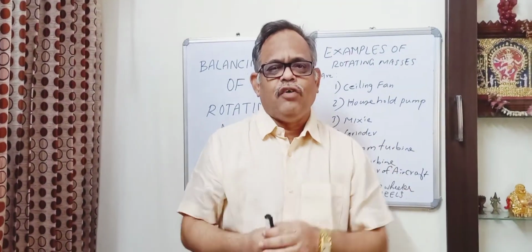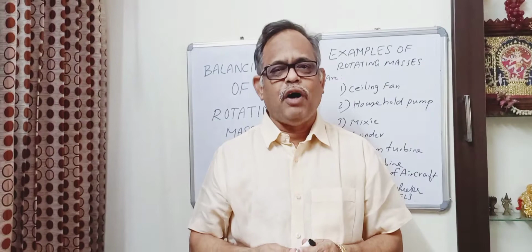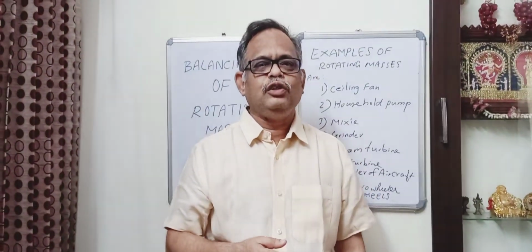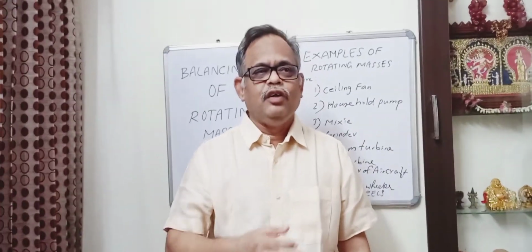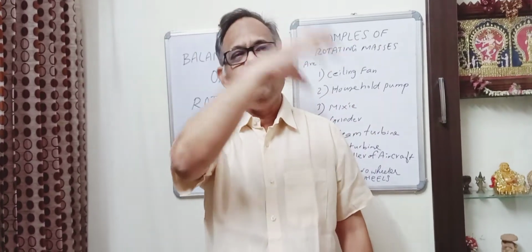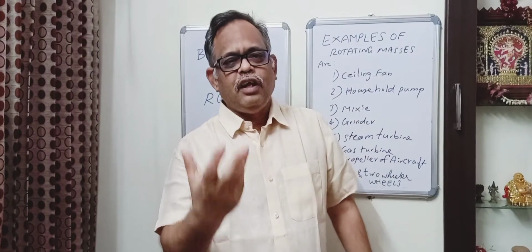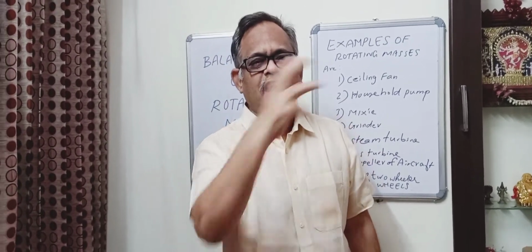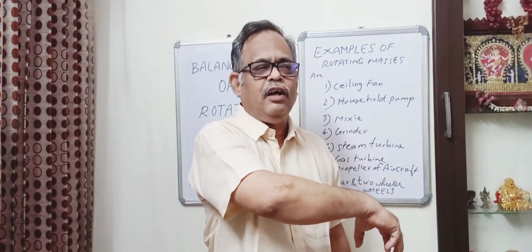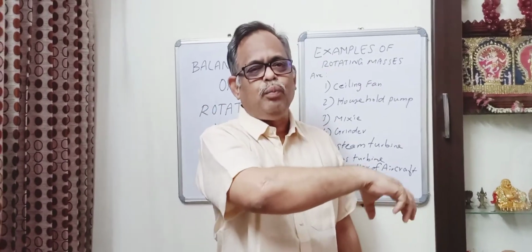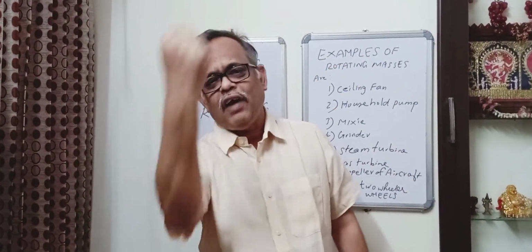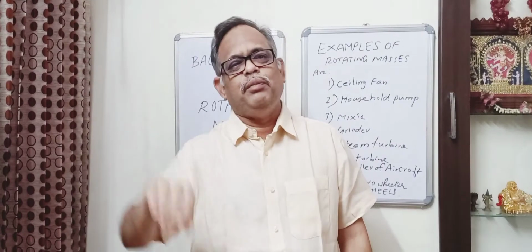Take the case of the induced draft fan in the power plant, right? In the case of the induced draft fan in the power plant, the ashes come along with the flue gas. The ID fan, or induced draft fan, draws or pulls the flue gas from the furnace and sends it to the chimney, right?